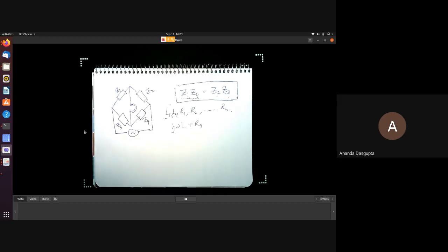What I did not really talk about too much was how useful each bridge is. Because then the question really would be several things. Is the bridge easy to balance? Those of you who have done Wheatstone bridge in your lab, most of you have, right? You would know that it's pretty easy to balance. There's a very simple standard rule to follow. When the galvanometer deflects to the right, you know you have gone too high. Because it deflects to the left, you know you have gone too low. Then you essentially carry out the bisection procedure until it does not deflect at all.